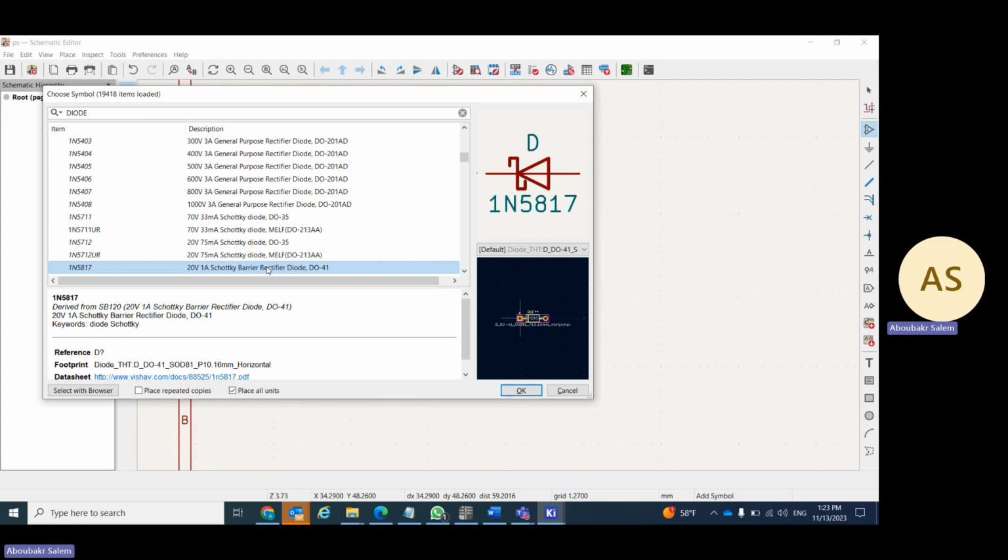So a general purpose diode you cannot apply, for instance, with rectifiers, controlled rectifiers, or inverter circuits with relatively high frequency, like 20 kilohertz. It will not turn on and off quickly like the Schottky diode, so we have to use a Schottky diode in that case. In the power supply, actually, we have only a frequency of 50 or 60 hertz. Here in the United States, we have 60 hertz only. However, using high frequency is not going to make any problem for us, so you can still use this Schottky diode.